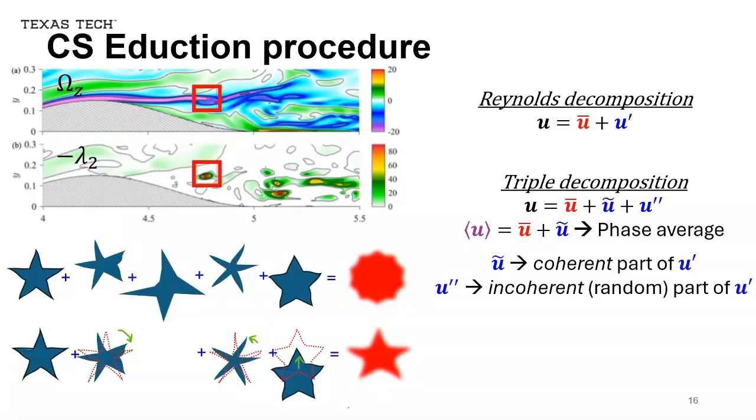So imagine you identify the structure features that you care about, but there's not one realization identical to each other. Let's say these stars, you see that I am considering this as representative, the features that I want to capture, which I think are the important coherent structure of the flow. If I do a phase-locked ensemble average without considering the misalignment between the two, this phase average will give me a featureless set of average, right? It will be just like a circle.